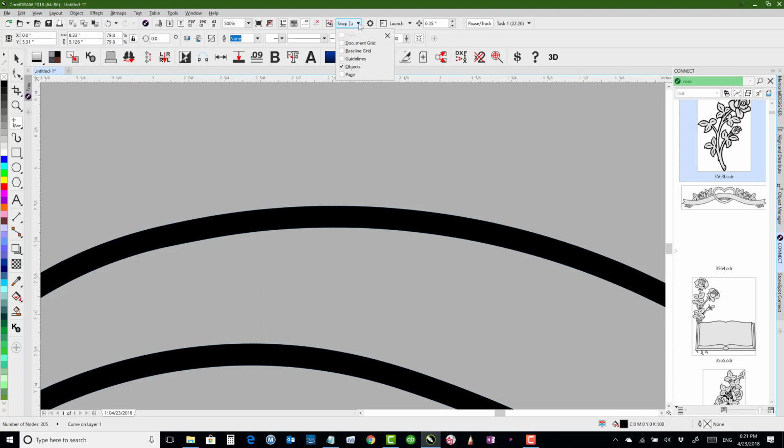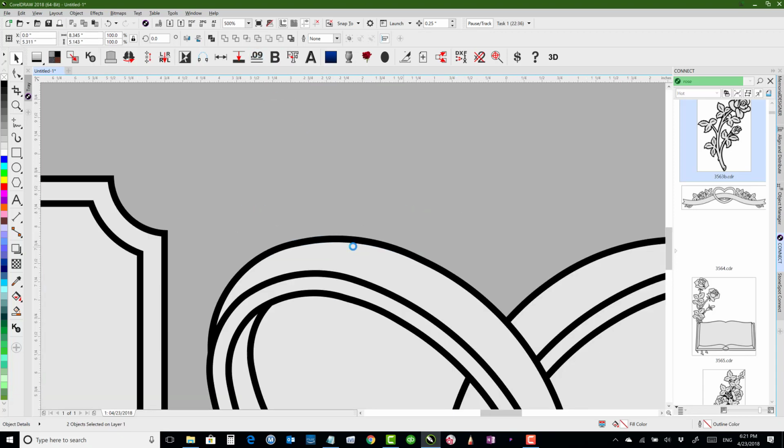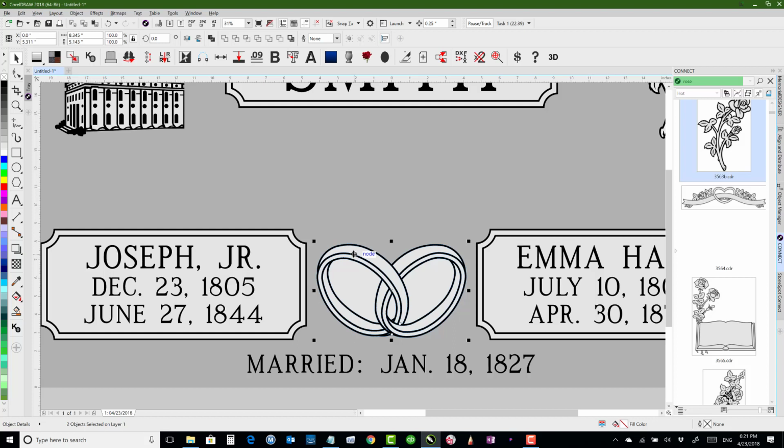I've got snapping set also, snap to objects. So if you don't have snapping, you won't be able to see where it says edge. Click there, then I'll click back down here. Click on my pick tool, shift select the part that I had combined, and then run blastable, which is this one here. And blastable will then resize that to make sure it's 0.09 inches.